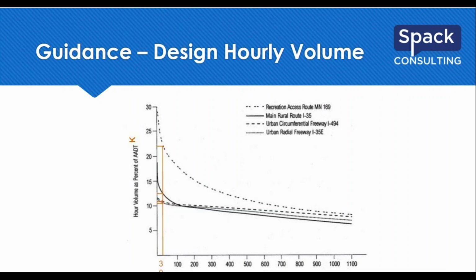is if you look at that 30th hour. So along with that 30th hour, when we're looking on a normal roadway, normal intersection, that 30th hour isn't on the weekends, isn't on the middle of the day. It's typically a normal Tuesday, Wednesday, Thursday during the PM peak hour is typical. That's why most studies focus in on the evening peak hour as their design hour.